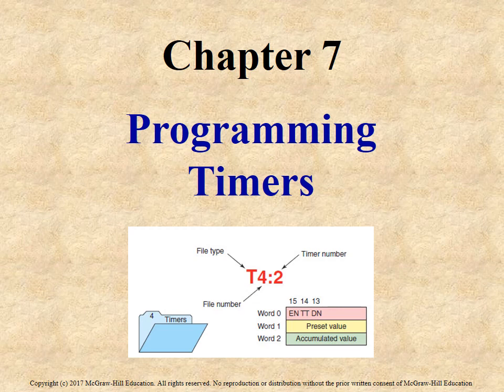Addressing is a little bit different than what we see here on the page, but we'll be going into that as well, so you'll have a solid understanding. But when you're dealing with the 500 world, the T4 is designated as the file number for timers. In the 5000, we can call it whatever we want. We can call it Joe's timers or Fred's timers, whatever we wanted to call it. So it doesn't have to be a T4 designation.